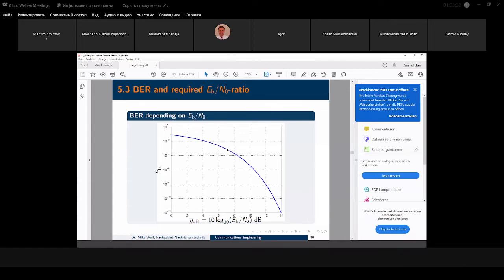In practical implementations of these forward error correction schemes, even if you do hard decision, for instance if you use Reed-Solomon codes and add only 7% redundancy, you have to increase your bit rate by 7% compared to the uncoded transmission, and then you can aim to switch from a bit error probability of 10^-12 to 10^-3. This is the gain you can obtain with forward error correction.